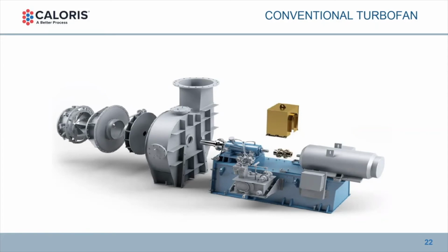In today's turbofans, we're getting an extra 2 degrees or more compression ratio off of the same size impeller because of different materials of construction, super duplex stainless that allows for a higher wheel speed, and they've also done some very good dynamic modeling on these impellers and modified their shapes and designs to get a little more compression out of the same wheel speed.